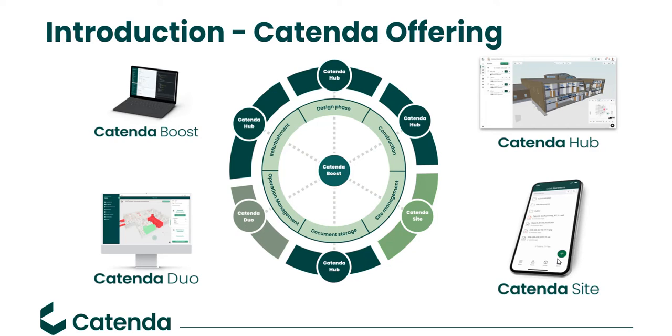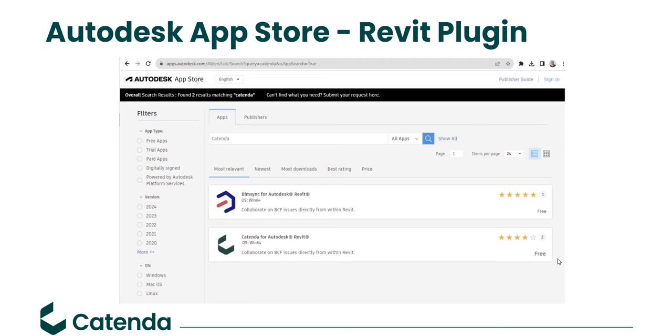As I mentioned before, the main focus is Catenda Hub and how Catenda Hub and Revit come together to offer you an innovative way of doing design coordination, and most importantly, an open way. So the first thing you need obviously is the Revit plugin. This can be found on the Autodesk App Store. You just type in Catenda and you will be presented with the Catenda plugin.